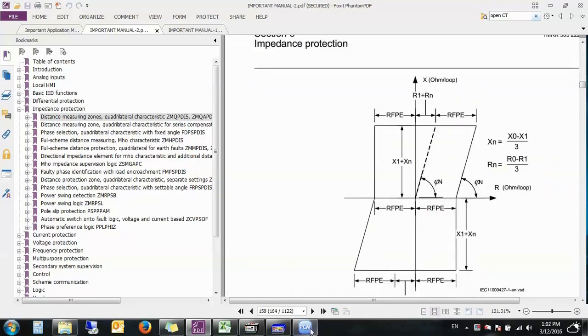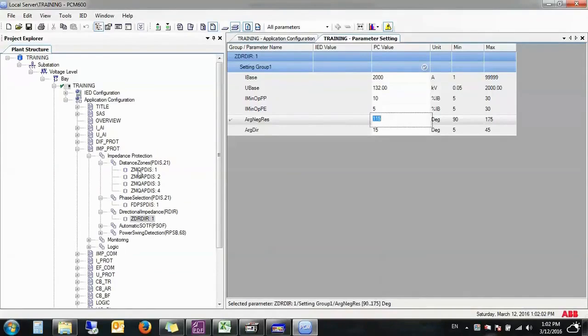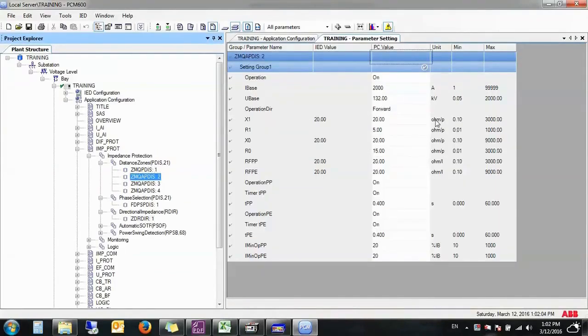The only information is that these values are primary, so you must convert them in terms of the CT ratio and the VT ratio, or divide by the CT ratio and the VT ratio. Do not think about converting from primary to secondary. You almost just divide by the CT ratio and the VT ratio, or multiply the CT ratio by the VT ratio. You can solve the problem simply and quickly. As you convert it, like converting to secondary, it will become clear to you.